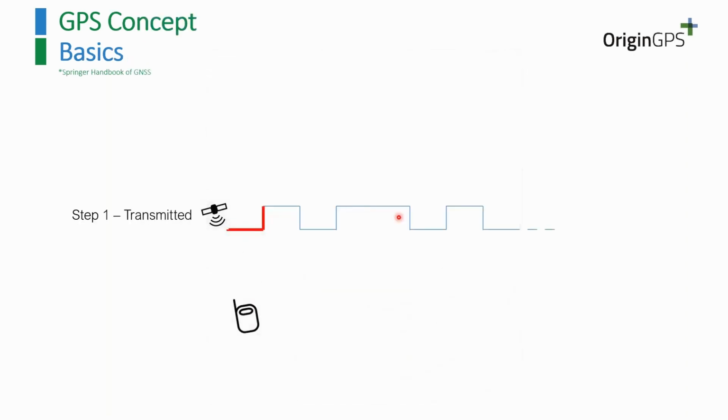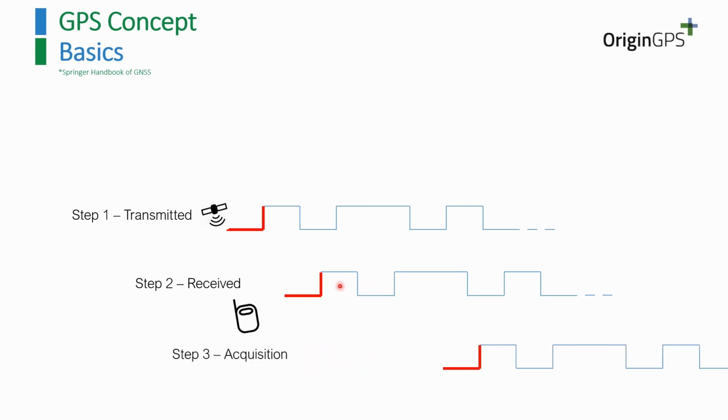If we go into the satellite information, it is transmitting bits of information. Our receiver is getting the information with a delay. You can see it over here. And then the receiver should calculate and make the acquisition process to be in correlation with the received signal.